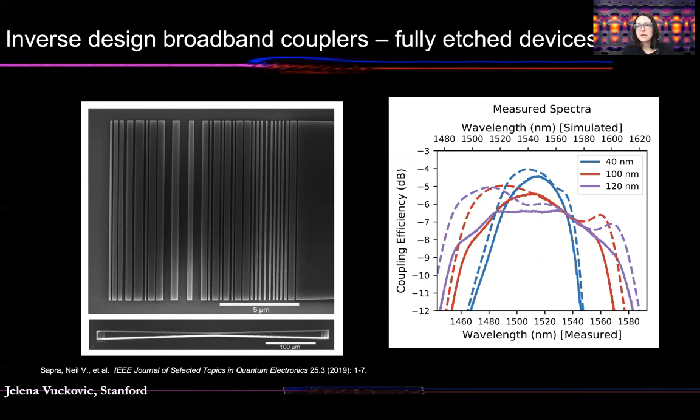Apart from the stage of the accelerator itself, there are other optics components that you need to design. And one of the key components are grating couplers. Of course, we use grating couplers many times in our photonic integrated chips, but this is a very different type of grating coupler because you need to couple short laser pulses that have large bandwidth, and that's not what we typically have to deal with in optoelectronics. And on top of that, you also want to design this grating coupler to minimize your laser-induced damage. So you want to minimize concentration of electric field inside of your semiconductor so that you don't really induce the laser damage. And that's what we do.